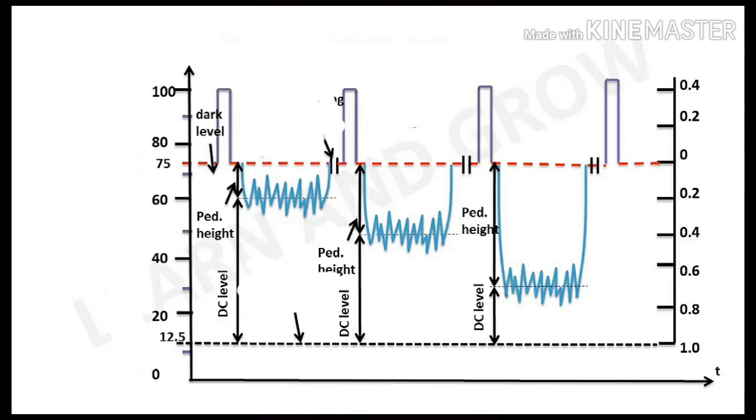The signals are displayed at intervals between the end of one field and the next. To illustrate what happens during the vertical blanking time, the two signals displayed one above the other are the same, except for the half-line shift between successive fields necessary for the display of interlaced odd lines.